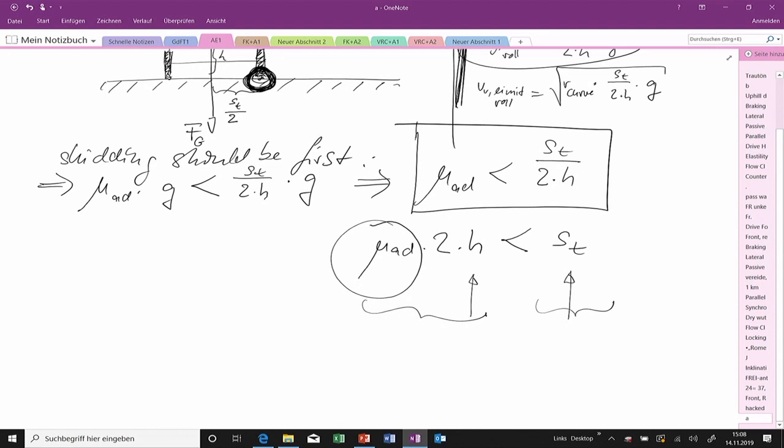So if I excite the car with an appropriate steering action, with the right frequency, and the frequency is about between 1 and 2 hertz. Yeah? 1 and 2 hertz. So that's a steering frequency which a person is able to do. It's faster than normal steering, but it's not impossible. So I think everybody can do steering activities with up to 2 hertz. So it's possible to excite the vehicle exactly in its rolling frequency.